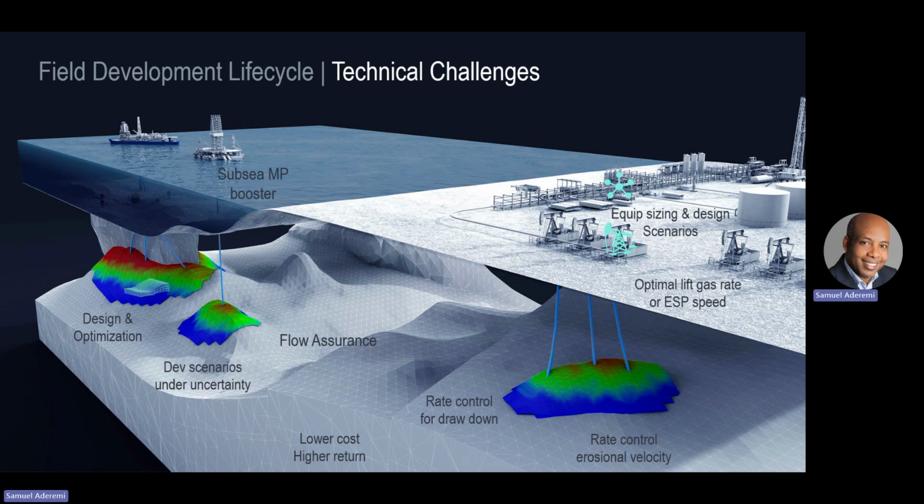Those boundary conditions that we usually specify as a constant value, that is far from the reality. In many assets that we work with, especially in the offshore development, all the reservoirs ultimately flow into the same production network. They share the same subsea system. They are constrained by a single platform, the risers, the topside with the fixed capacity limit. And this is where the standalone optimization breaks down. No, we can't do that. We can't work in silos.